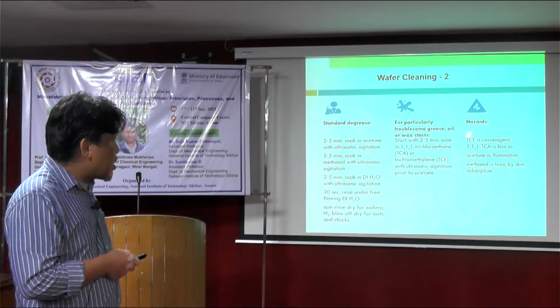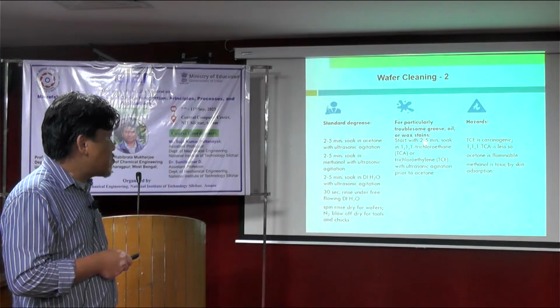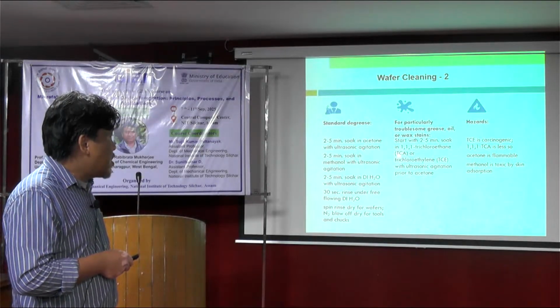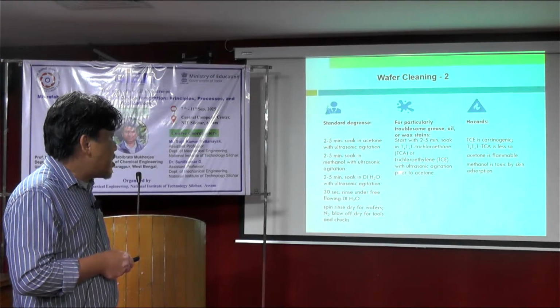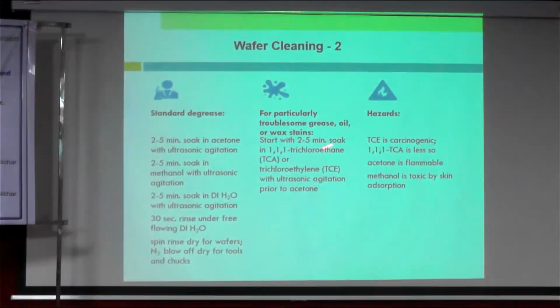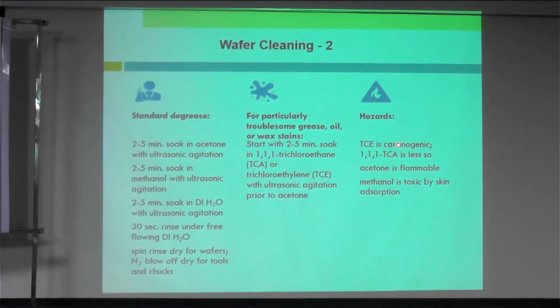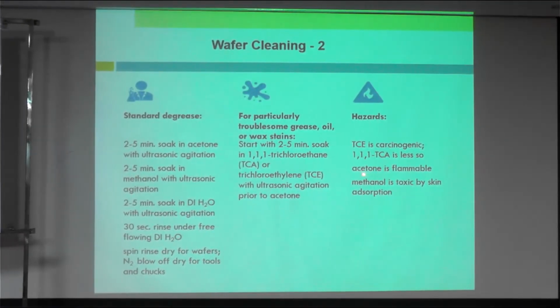For particularly troublesome grease, oil, or wax stains, start with a 2 to 5 minutes soak with TCA or TCE with ultrasonic agitation prior to acetone. So this is a harsher process. TCE is a kind of carcinogenic. Acetone is flammable. Methanol is toxic by skin absorption. So we must be careful. That's why in the clean room we use mask and we use gloves, etc. PPE.